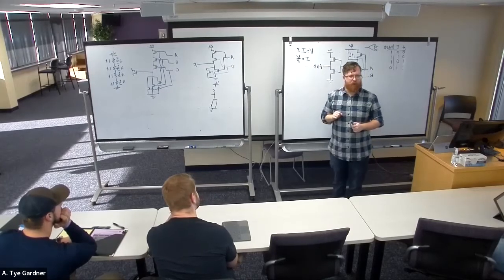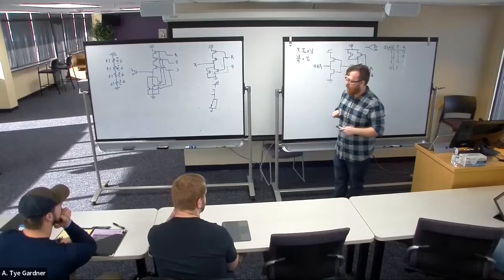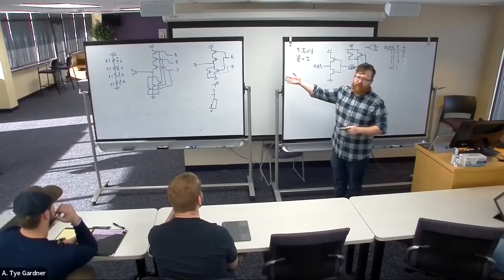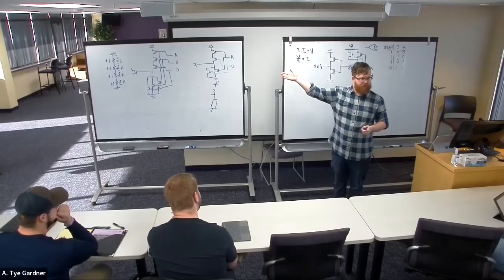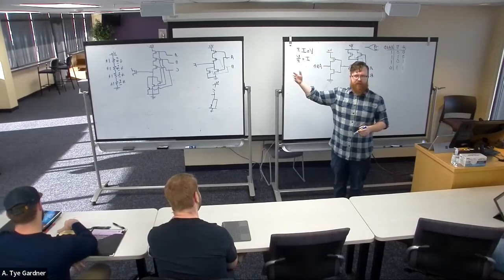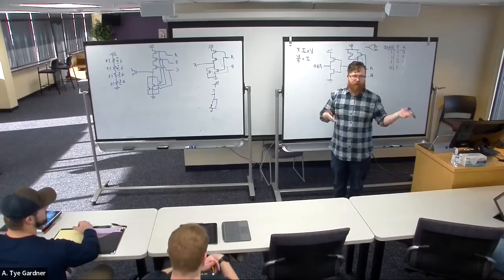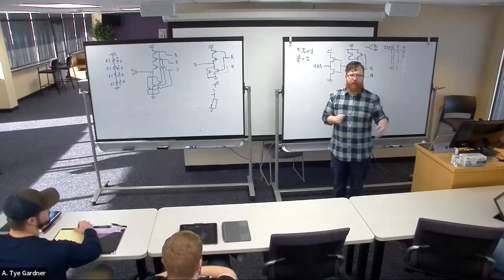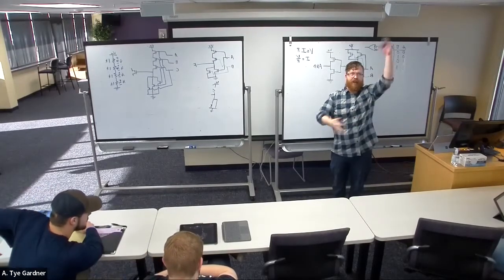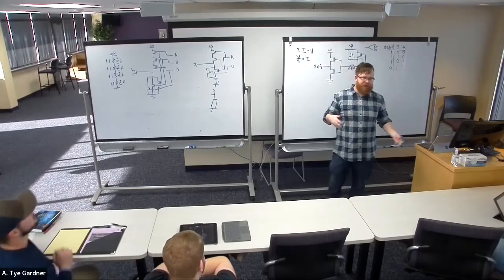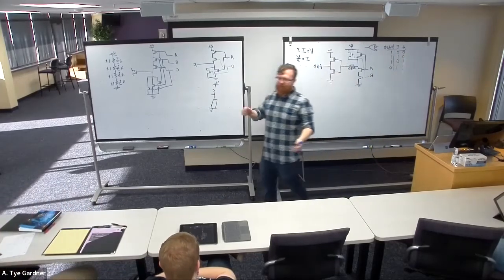I just like you to know where you're kind of going, right? That's all this is for. So there's going to be some limit on how big we can build these, which is why a lot of times you see us build a 4-input AND gate out of 3 2-input AND gates, because there's a limited amount of voltage overhead that I can use to stack these up. That's why. We're not torturing you with this arbitrarily.